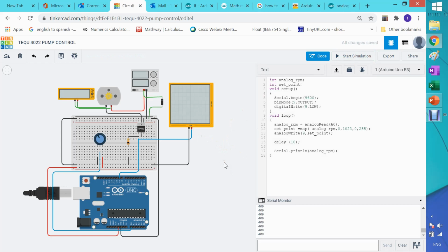So again, the better approach for DC motor control is, instead of using analogWrite, to use my own duty cycle based on my own cycle time, whatever cycle time you want to test, for example 100 milliseconds, and so forth.